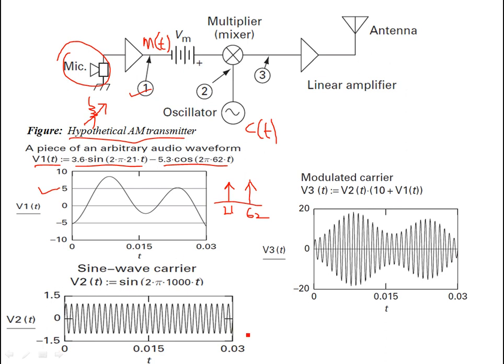Now the carrier signal is at 1000 hertz, far away from the modulating signal. So this is DC, and this is 1000. And again, you have it at minus 1000 as well. It's a real signal, so the spectrum of a real signal is symmetric. That's always the case. Similarly, I've shown the sidebands over here. You will have minus 21, and you will have minus 52 as well. So 2 more sidebands, symmetric spectrum, minus 21 and minus 52.